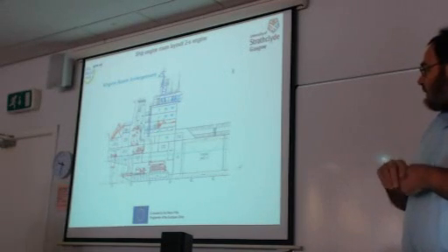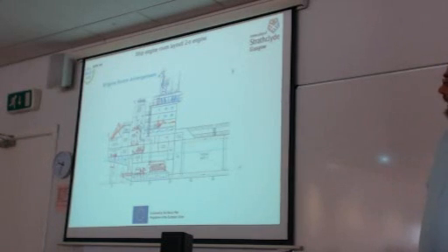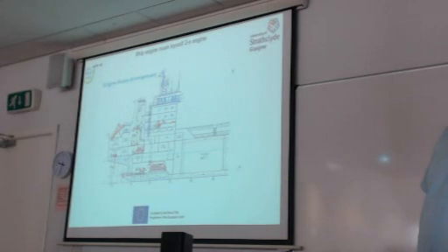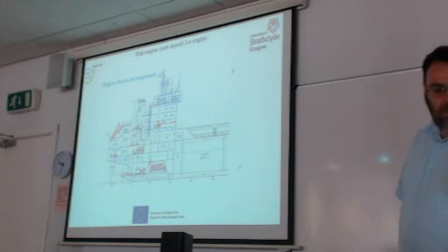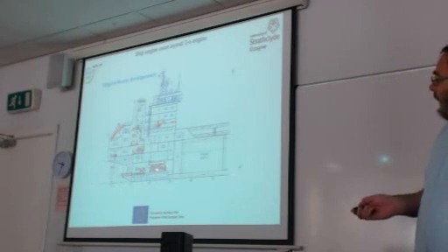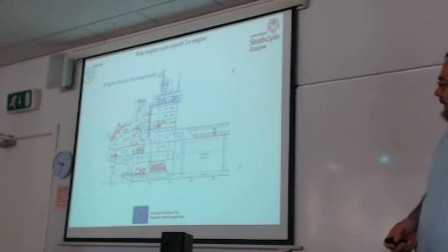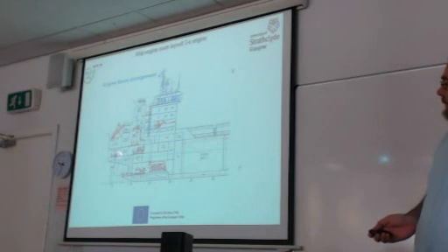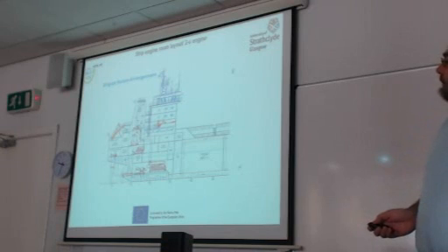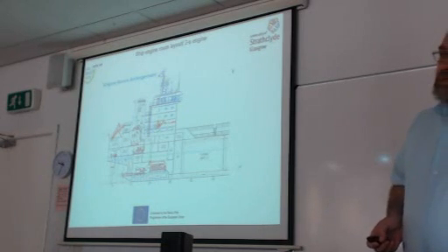So let's proceed by showing some typical engine room arrangements. This is the typical arrangement on board a merchant ship with one, usually two-stroke, large engine as prime mover, connected with the ship propeller using the propulsion system. In smaller ships, we can have one medium speed engine, but in this case, a gearbox is needed between the engine and the propeller. Apart from the main engine, we have the auxiliary engines, diesel generators, usually 3, and of course, an auxiliary boiler depending on the ship type.